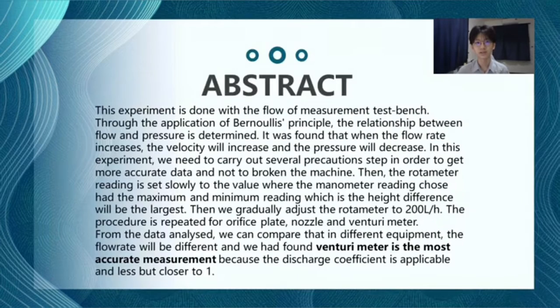For the abstract, this experiment is done with the flow measurement test bench. Through the application of Bernoulli's principle, the relationship between flow and pressure is determined. It was found that when the flow rate increases, the velocity will increase and the pressure will decrease.